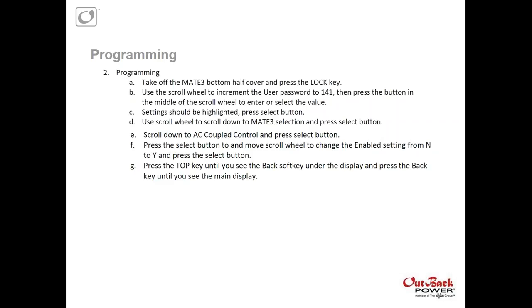So one of the things that you can do is replicate essentially a couple different stages of charging by having a couple different relays that fire at different voltages. Instead of going from 100 to 0 on the production from the SolarEdge inverter, you may decide to go from 100 to 50 or 60, depending on the output that you're after, to replicate an absorbed charge on the batteries.